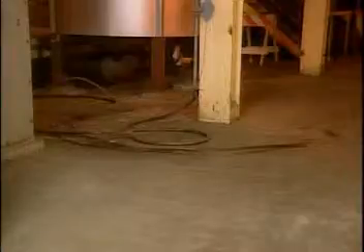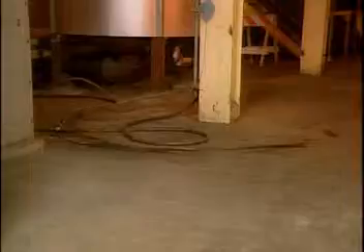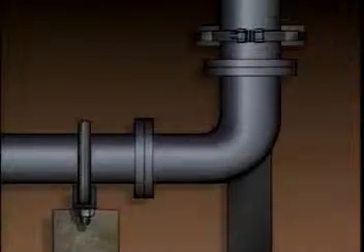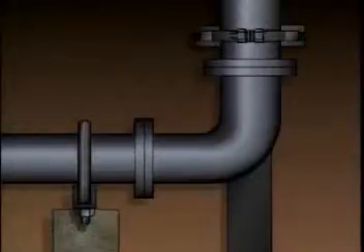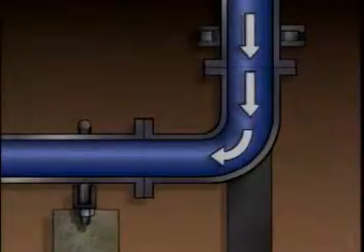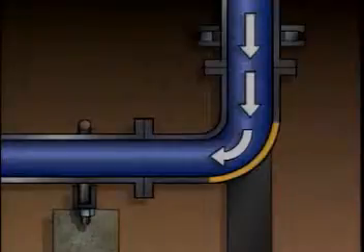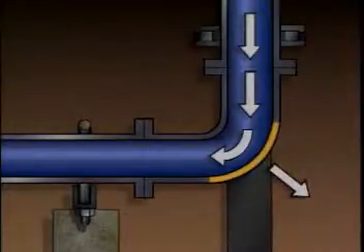In the plant, an example of the third law can be seen in this demonstration using a compressed air hose. The movement of the hose is caused by a reaction force that's produced when air flows rapidly out of the hose. Another example is the pipe supports that keep pipes from moving when the fluid flowing through them makes a turn. As the fluid makes the turn, the pipe exerts a force on the fluid. And the fluid exerts a reaction force on the pipe, causing it to try to move in the opposite direction.